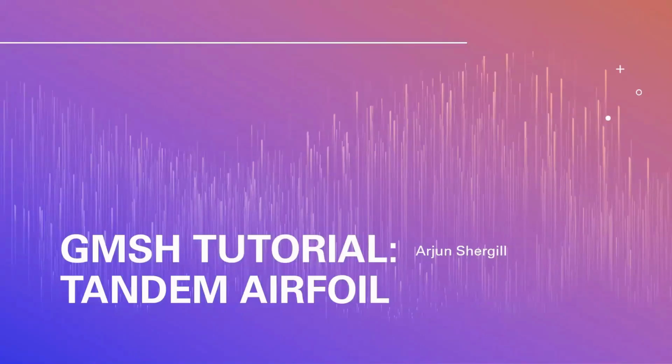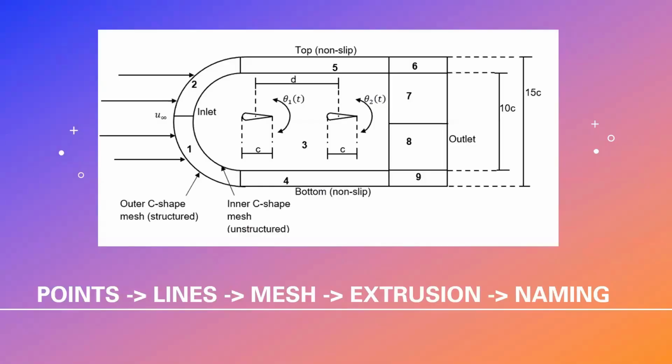Hello there. My name is Arjun Shergil, and I'm going to be showing you how to make a tandem airfoil on Gmsh. So the mesh is going to look something like this. We're going to have an inner C-shape and an outer C-shape domain, and they'll be connected together. We'll have an unstructured mesh around the two tandem airfoils, which will be teardrop.